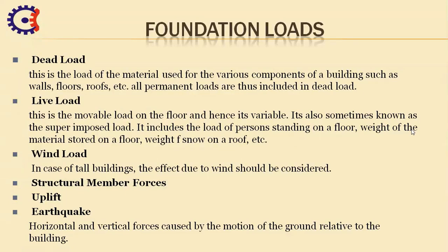Next is structural member forces, uplift forces and earthquake forces. So basically in these three parameters, during an earthquake, lateral earth pressure acting upon retaining structures temporarily increases. The parts of the structure below grade, all retaining structures and bracing systems, are subjected to the lateral earth pressure.